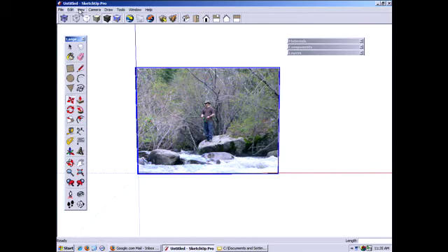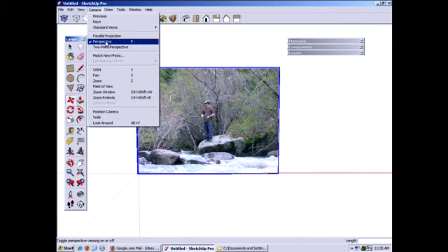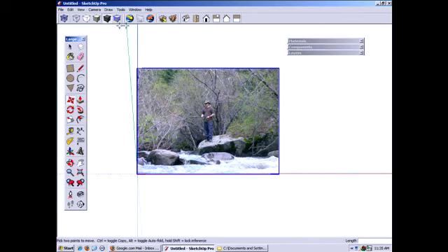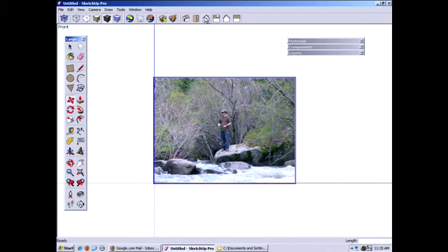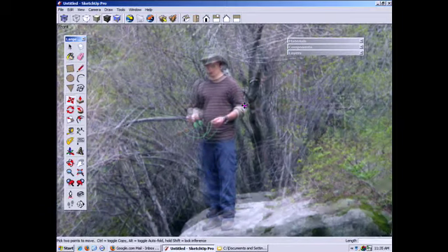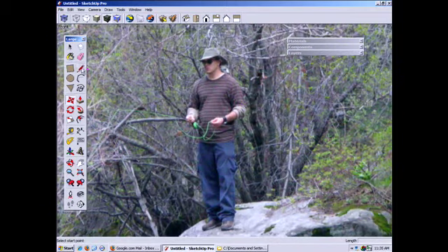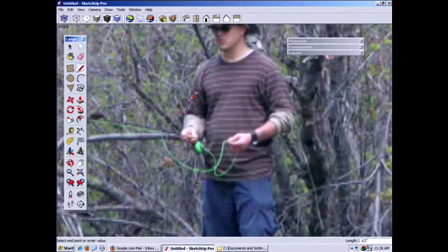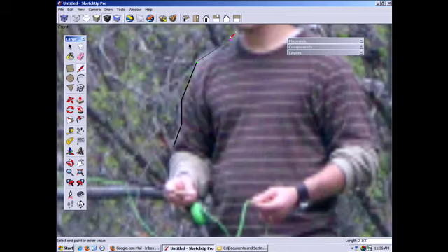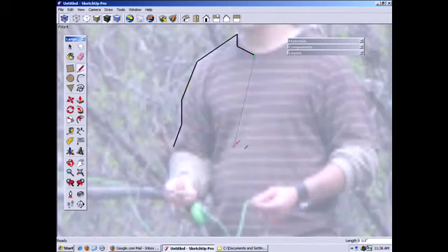I'm actually going to go up and turn perspective off, and then choose just a front view, which again, just for the purposes of making these, I find makes it a little easier. The last thing is, as we start to trace this out, some of these edges are easy to see, but it becomes even easier if you turn X-ray mode on. Then you get it grayed out, but your edges really stand out. So I find that to be useful as well.